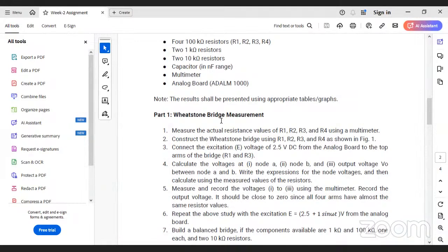We just need to see the plot, for you to understand the effect of attaching a capacitance to the load, so that the low pass filtering will be there after you add the capacitor. So you can use any value, but make sure it is in the nanofarad range. That is it. It is up to you.